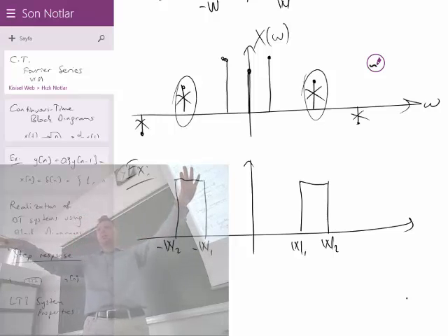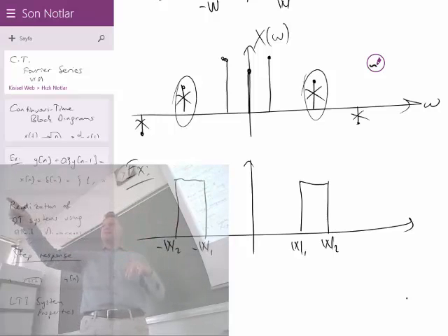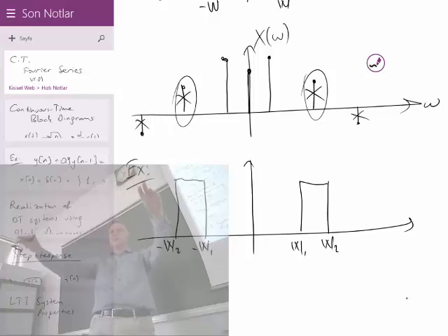They pass through multiple channels, and at the end of those bandpass filters, they measure the magnitude. If the magnitude is this much, then they generate this much VU meter output of LEDs. If the bandpass output is low, it means the harmonic corresponding to that bandpass range is not very strong, so it will be a lower LED marking.